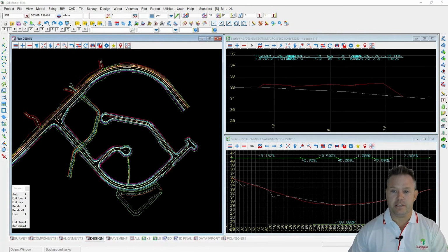Okay, last feature for me, MTF Recreate. The MTF Recreate tool was originally created for construction surveyors that received 12D model design strings for the design surface, but then were required to produce the subsurface grading for pavement themselves, but didn't have the actual MTF file. So this is reasonably difficult to do and requires duplicating the design. If you want to see more on this, feel free to check out Peter Taten's presentation on pavement construction in the survey room.